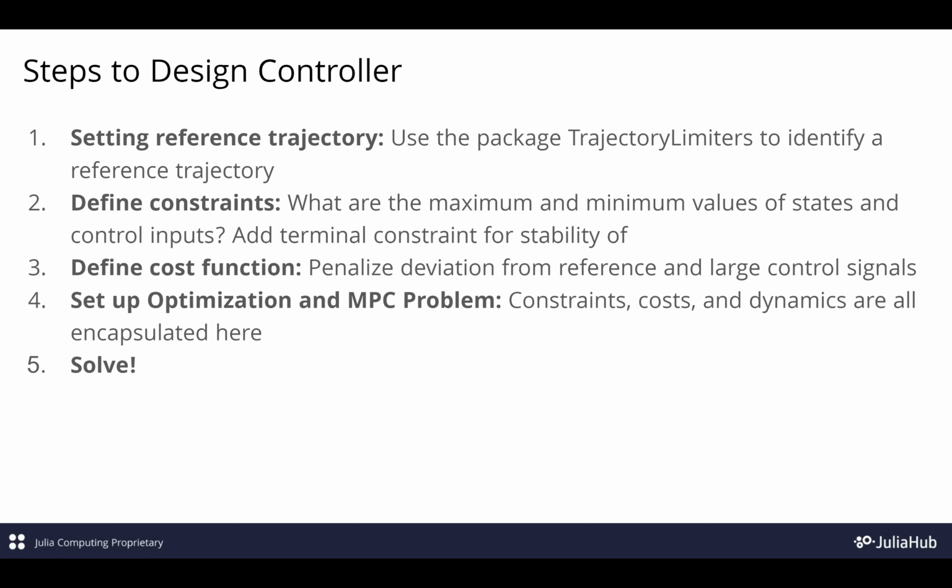And can I then add some sort of terminal constraint? So I know where and how this car starts out, but where and how does this car end? What is the final position of the car? That is something you can add as a terminal constraint. So you can see we do have a primitive for this, the terminal constraint primitive. While designing other types of controllers where you want a system to be constrained to a particular type of steady state, you might see how this type of constraint is useful. That's an independent line of thought. We can talk about that separately.